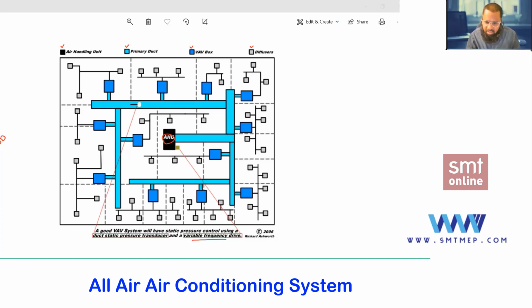And as the speed increases or decreases, the power consumption also varies, right? Yes, sir. The first difference compared with the CAV AHU: in the VAV AHU, you will find a VFD drive fan motor. It means it is VSD. It can increase or decrease the motor speed, and speed is directly proportional to the flow. As the speed increases, meaning RPM increases, the flow rate increases, right?